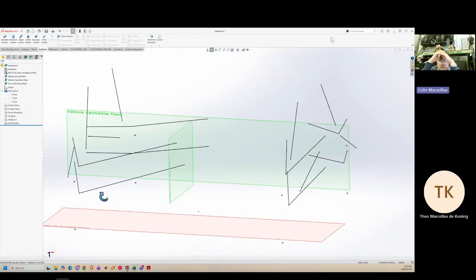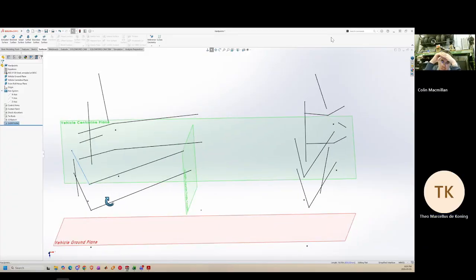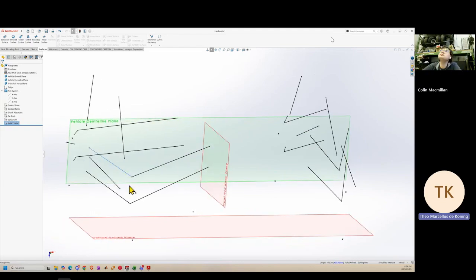Okay. So this is treating each of these links as a 2-force member. Basically only tension and compression going through these links. So you'd have an axial force pointing in the direction of the sketch here, right? Into the sketch?